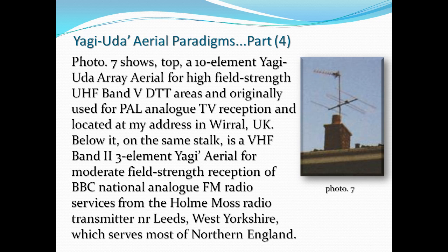Switching the tuner from stereo to mono mode is necessary as I live well outside the official transmitter coverage area for this VHF FM service. That is to say, the signal strength, that's the electric field strength received at my Wirral location, is below the value set by the BBC for adequate FM stereo reception, i.e. below 54 decibels relative to 1 microvolt per meter. This figure equates to an absolute electric field strength value of just over half a millivolt per meter.